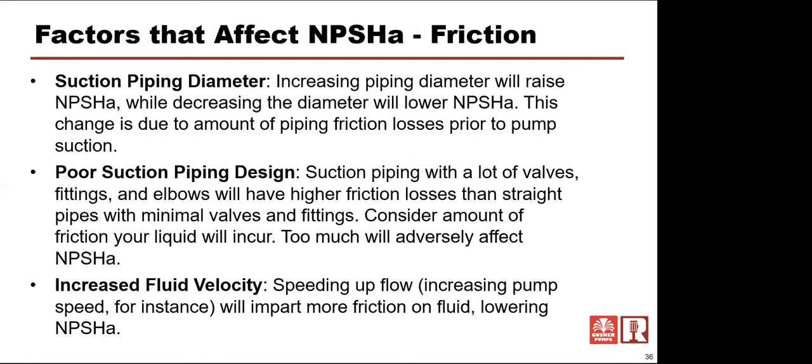But this is something you're typically going to pull off of either a pipe sizing program, and there are a couple available as apps that are inexpensive or free, or off a chart somewhere, perhaps in the back of a pump manual. Somewhere or another, you should be able to figure out what the friction loss through piping is.